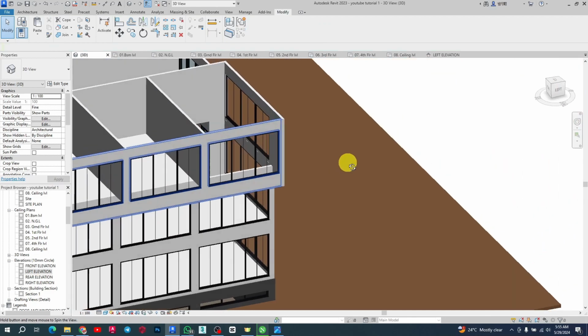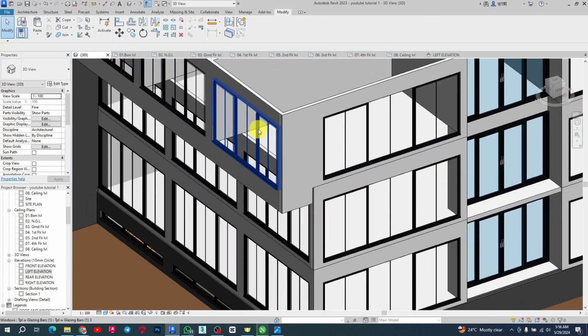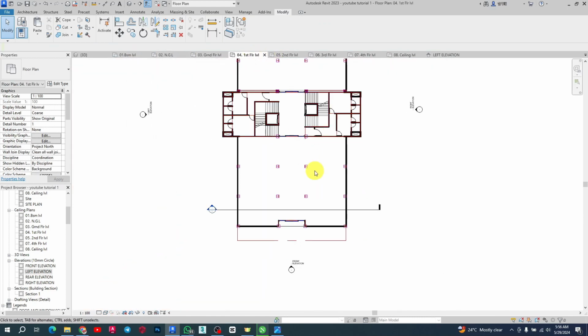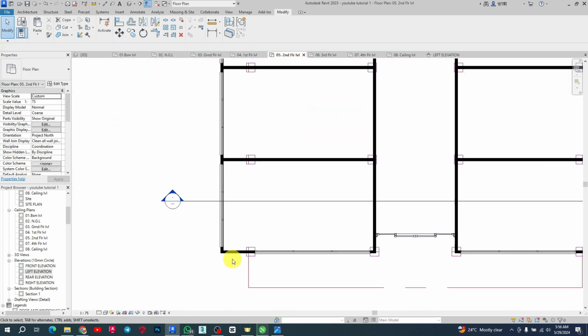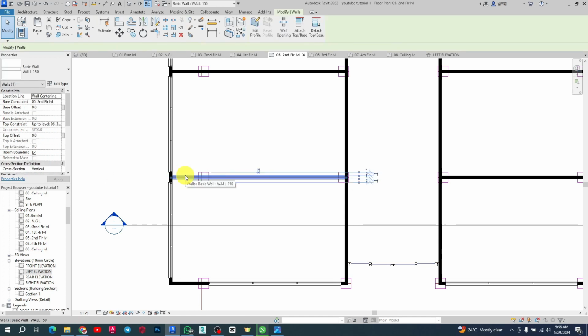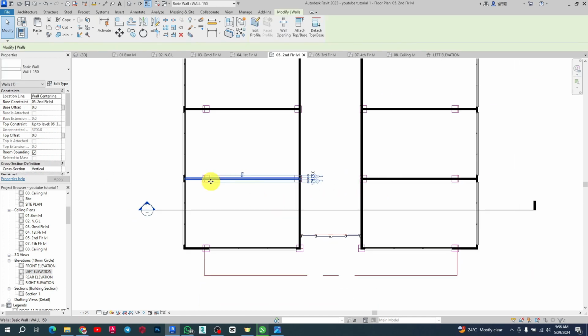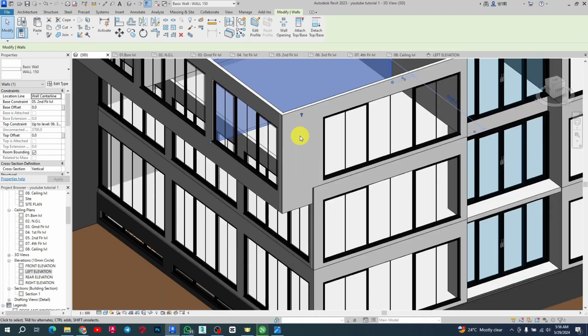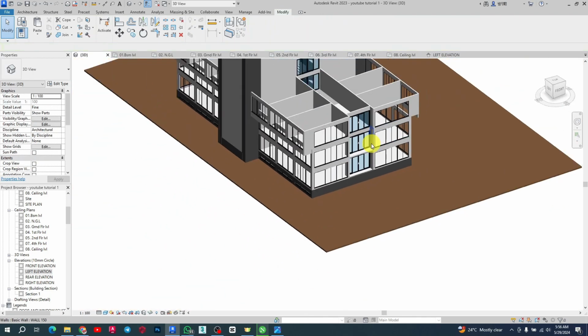Again, if that 700 looks deep for you, maybe the beam at the cantilever, the beams that go outside, because we are going to be having a structural beam that runs like this. The main supporting beam runs like this, so you can have 700 and then it drops the height again to carry this cantilever side. You drop the height to 500, so you'll be 700. You have the step beam there, right? So you can take this one 500 if that's something that you want. So let's just leave it like this, and in the next video I'm just going to go ahead and do the other part.